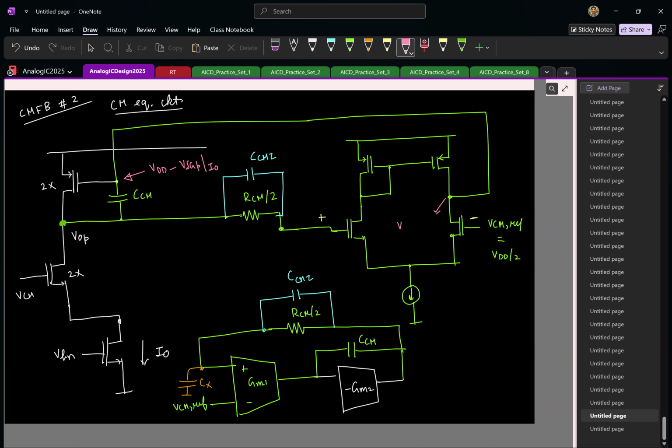So this voltage helps me, right? This is VDD minus VSG of a PMOS transistor at some current, right? Yeah, correct. As mentioned, even for this voltage would be some VDD minus, I'll say VSG of some PMOS transistor X at some current Ix. I call this 2 times Ix.